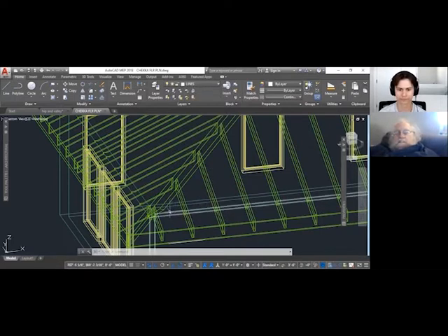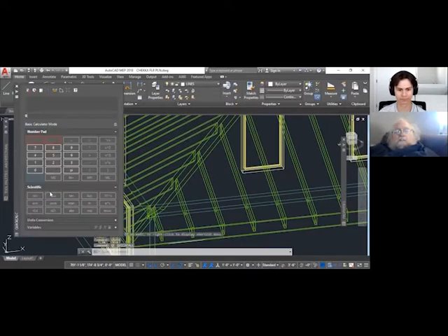And then I subtract the half thickness of my hip times 1.4142. You remember yesterday when we talked about the square root of 2? Right, and that's also the secant of 45 degrees. Exactly. You end up using the number 1.4142 so many times it'll become etched in your brain.